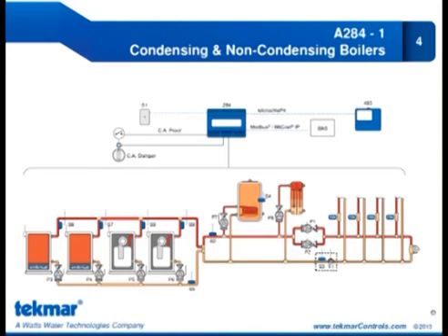Yeah, the key thing there is, if you just had one temperature, there's no reason to connect a 423 to a 284. Just use a 284 by itself. If you have more than one temperature, because the 284 only supports one Tecmar Net4 temperature, even though it supports 4 buses, those buses are for supporting up to 96 zones, but it's still defined as one boiler reset temperature. So if you have, say, staple up and in-floor radiant, then you'd maybe hook up a 423 or even a 402, for example.